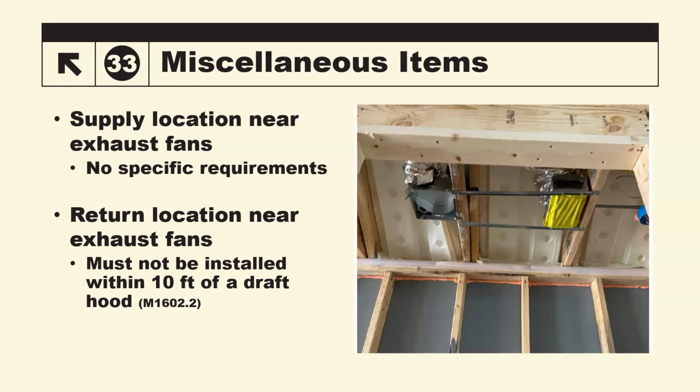So if that bath fan is installed, A, it's installed poorly with how the duct is running. B, if that's directly over the water closet, the toilet area, and that vent is now pointed directly at their head, that's probably not going to be very comfortable. There's just not a lot you can do with this, except, in my opinion, you'd point it towards the outside wall.